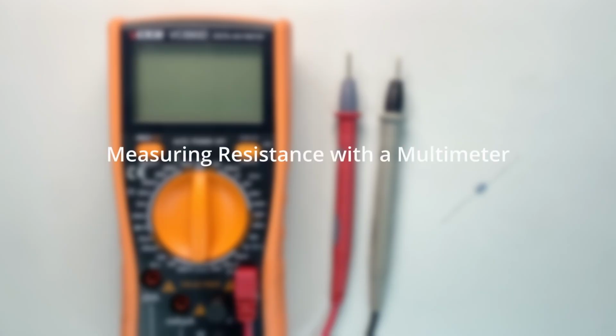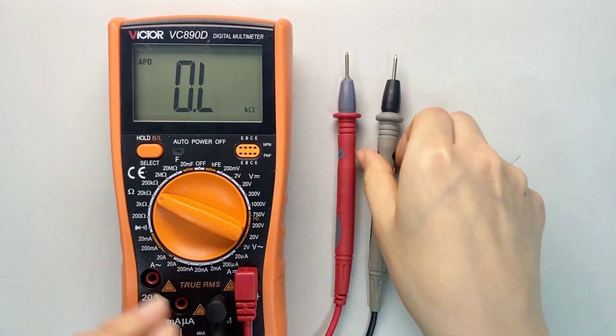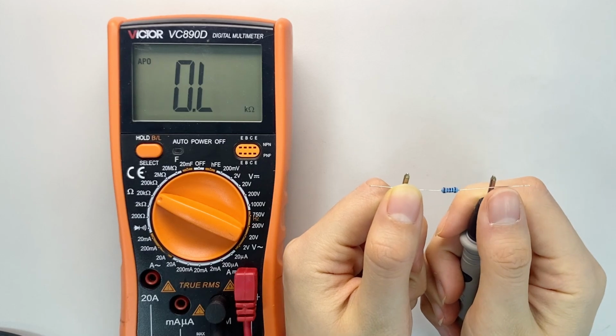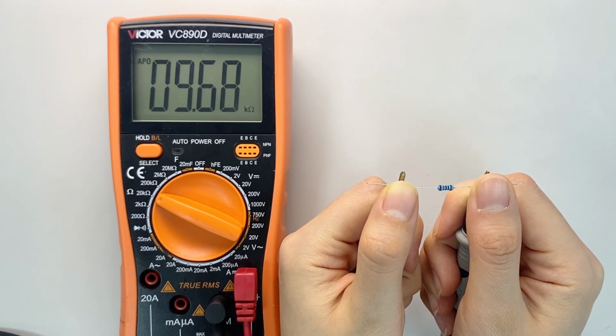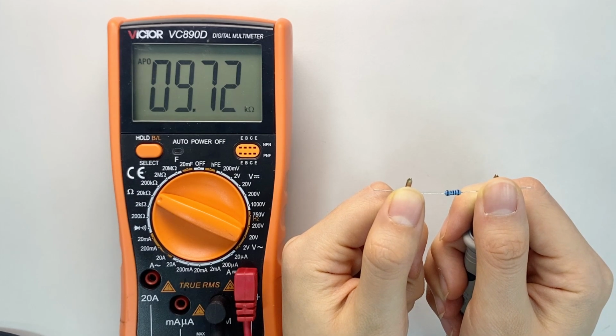Next, let's use the multimeter to measure the resistance value of a resistor. Set the multimeter to the resistance mode. Connect the red and black probes to the 2 pins of the resistor. Check the resistance value displayed on the multimeter, and you can see that this is a 10,000 ohms resistor. Compare the multimeter reading with the standard value from the resistor's color bands to ensure the measurement is within the acceptable error range.